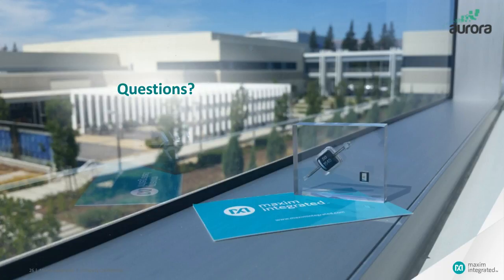Sure. So as I said, initially we build a circuit model for every cell string in the design. So we build an equivalent circuit model that's been developed and validated by a number of researchers over the years. And then essentially, for cell string level optimization in particular, we treat each cell string itself almost like its own panel connected to its own maximum power point tracker.